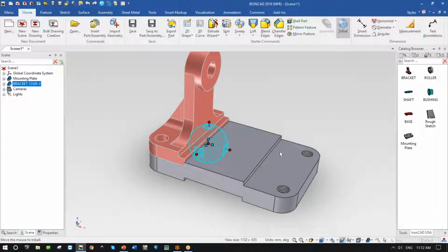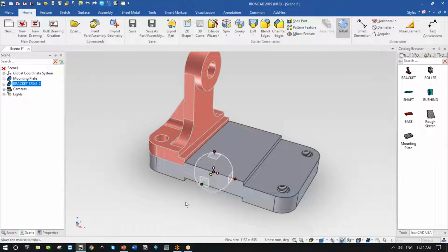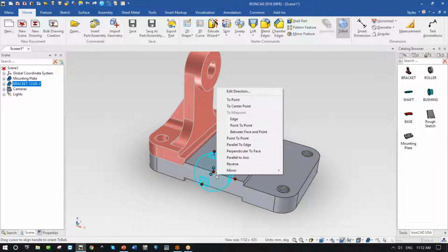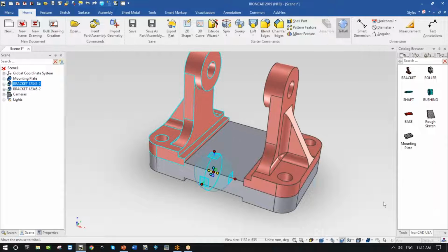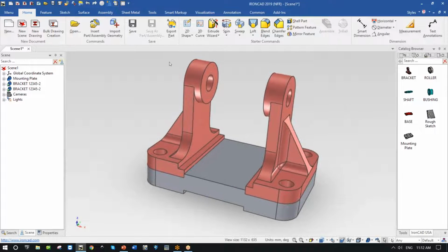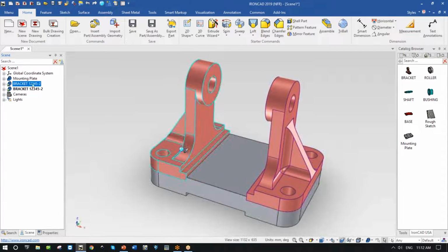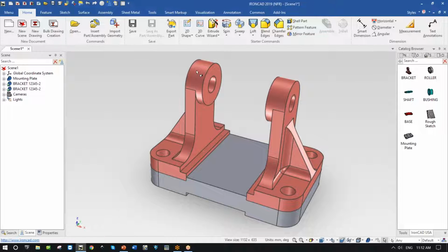Now, I need another one on the other side. So I can free up the tri-ball and simply do this. Say, take this tri-ball, put it at the center of my part, and then give me a mirror linked image of this thing on the other side. Simply takes this and copies it around the middle and puts it over there. Excellent for me. And we're already starting to build our, notice we've used this with drag and drop, bracket number 1. And how were these created? With the same technique. Cylinders, blocks, holes, extrudes, done.